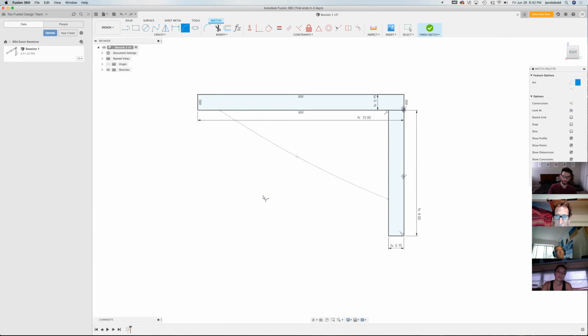You'll be left with this flexible line, and you can drag out to whereabouts looks good. Roughly there. You can see though this has got an undercut shape to it. It's going in at an upwards angle into the backer board, which is not ideal.